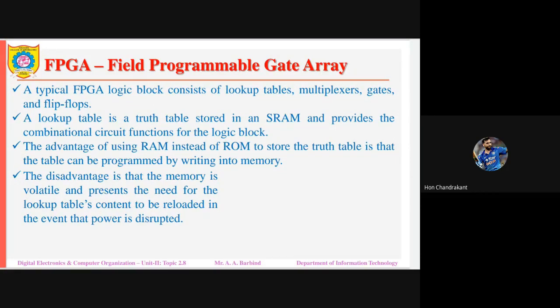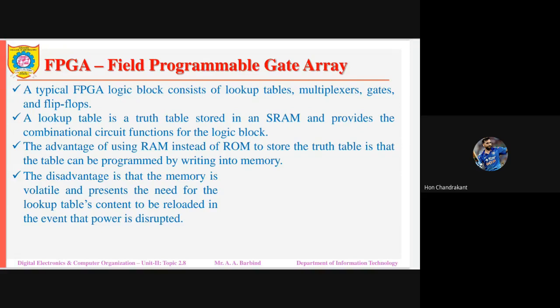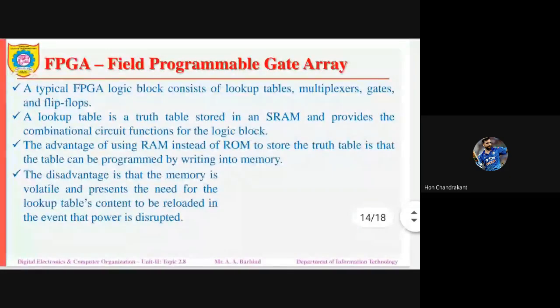Whereas in the PLDs, once you have stored something in the ROM, that is, you have made some connection or some disconnection, the functionality of that particular device is final. After that, you cannot change the functionality of the PLDs, or SPLDs or CPLDs. But in case of FPGA, you can reload the functionality. When you reload the RAM inside the FPGA, the functionality will be changed. So that is the major difference between FPGA and